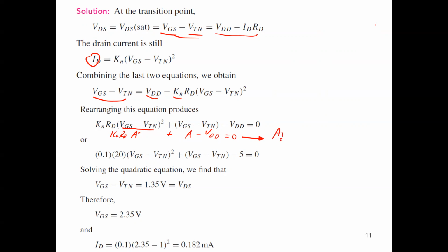We can get them from the equation as we discussed earlier. How can we get the roots of a quadratic equation? Now, guys, substitute with the constants we have. Finally, we will get two solutions. One solution would be accepted and the other solution is not accepted. Most of the time, guys, the other solution is either a negative value or another value which is in a non-saturation region, and we now consider the accepted solution as the operating point, the intersection.